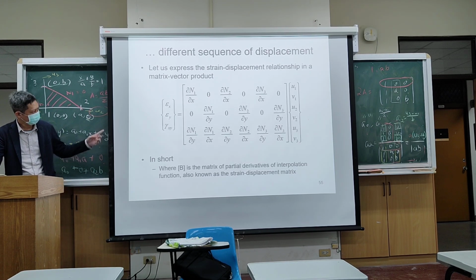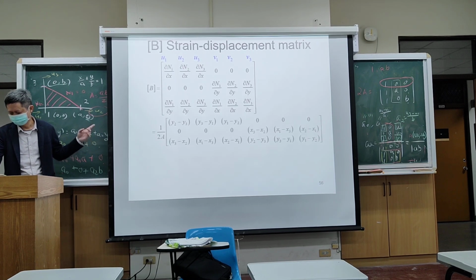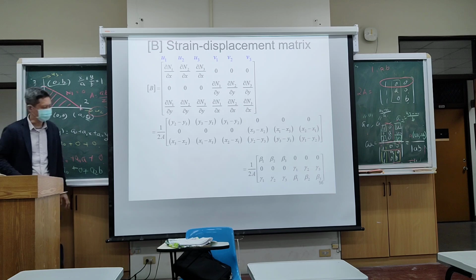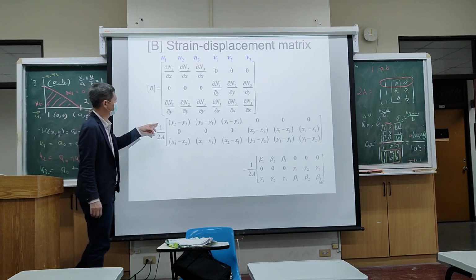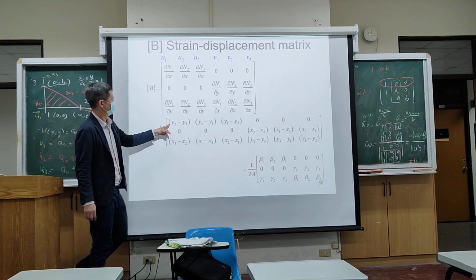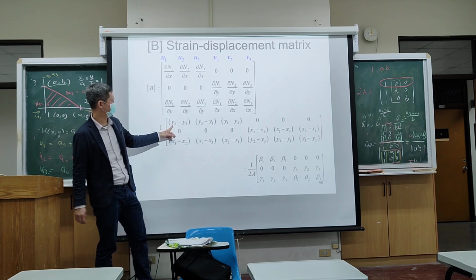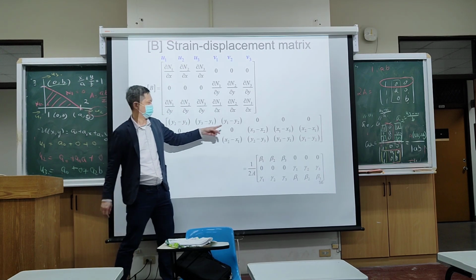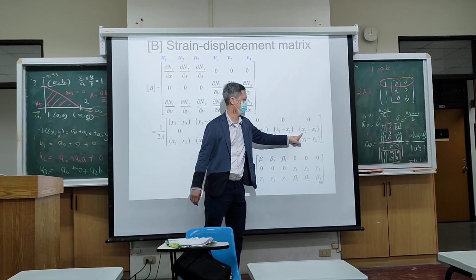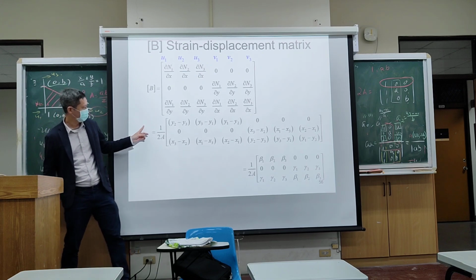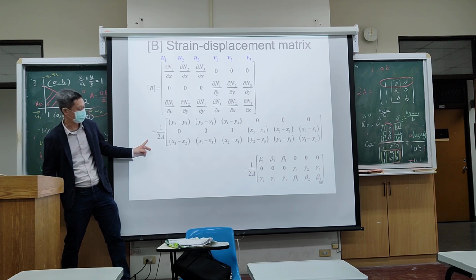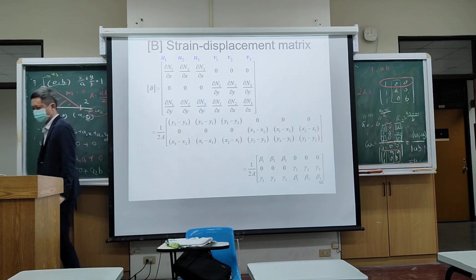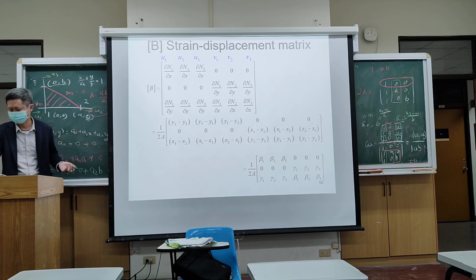Okay? And then finally, you come back to the expressions. You have this shape function, and then you have the B matrix being the gradient of the shape function. So if you group them that way, del U del x will have a coefficient solely depending on y. Del V del y will have a coefficient solely depending on x. Okay, these are the differences. And then del U del y plus del V del x will then have a coefficient of this. So for this part you really need to go back and derive it one time.